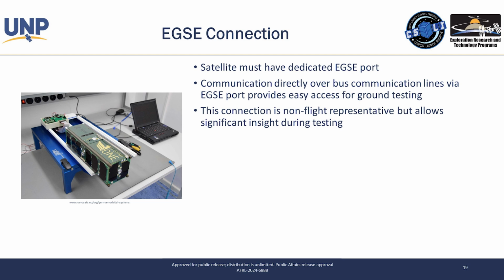So it is also very important to run functional testing over the RF interface in the actual flight config to show that you can accomplish everything. Your software engineers will get very comfortable with the GSE port and will be quite upset when you take it away from them and make them do everything over the radio.